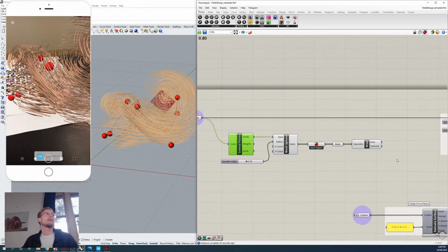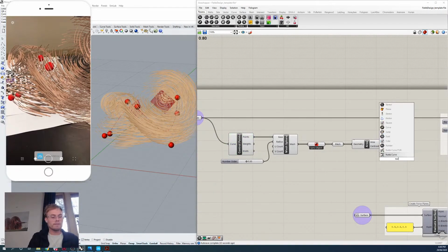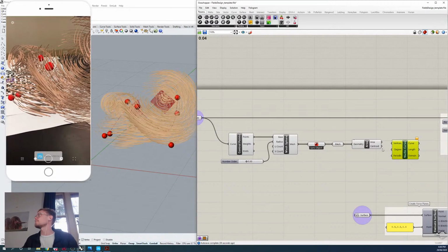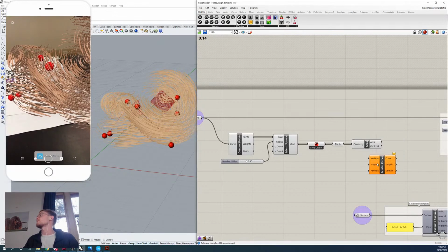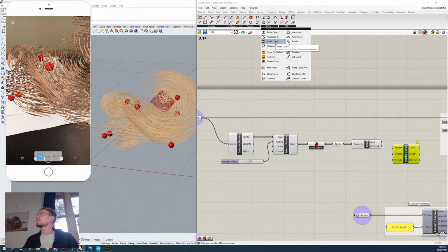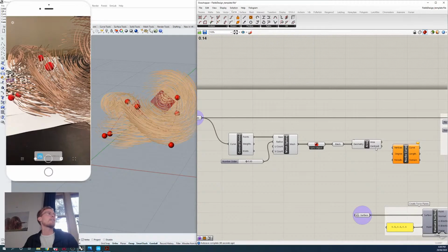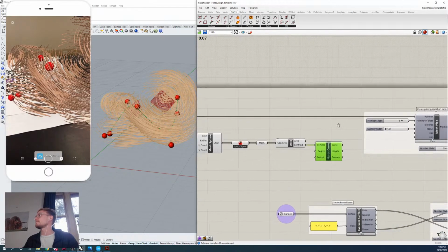Then I could go ahead and just create a NURBS curve like that. So just type in NURBS curve, and it's just that one that looks like a C. I think it's pretty high up in primitive from memory. I think it's spline. So there it is, NURBS curve there. And I want you to plug the centroid output from area into the NURBS curve vertices here.